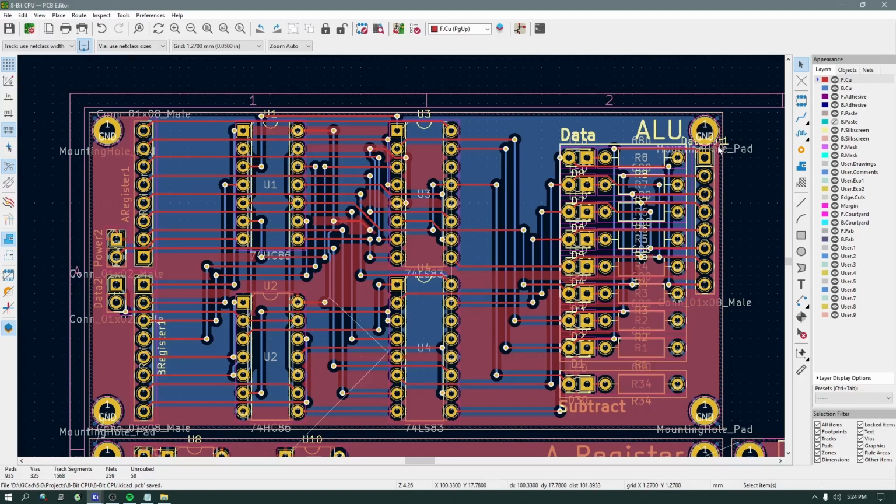The reason there are 4 chips instead of 1 or 2 is slightly more complicated. To subtract, you need the 2's complement of the B register. This is done with 2 XOR chips. The subtract signal goes to all the XOR gates and also the carry in of the first adder. The XOR gates are basically inverters with a special input signal. Since the output of the gate is high if one of the inputs is high, this creates an inverter.